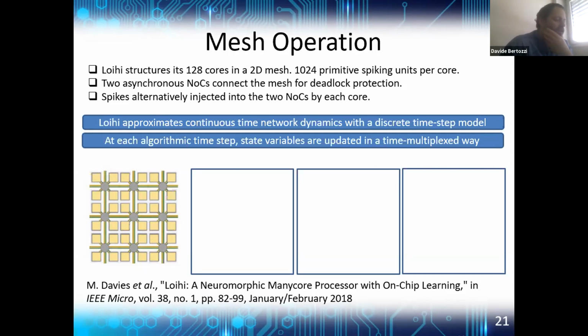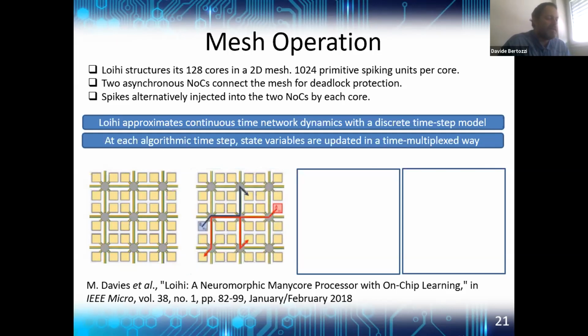Each core independently iterates over its sets of spiking primitives, and any neurons that enter a firing state generate spike messages that the NoC distributes to all cores that contain their synaptic fan-outs. Spike distributions for two such example neurons, N1 and N2 in cores A and B, are illustrated in this animation. The spiking neuron in neural core A is spiking with a fan-out of 2, while this N2 neuron in core B is spiking to a single destination neuron.